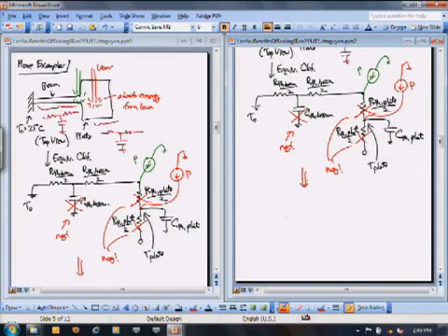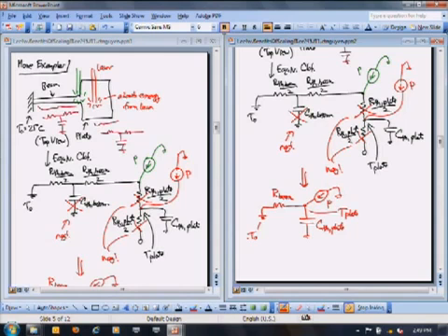where you just have the beam grounded there. That goes straight into the thermal capacitance of the plate, and the laser power comes straight into this. Okay? And this then becomes my T plate, and that's my T0. Okay? So that really is the equivalent circuit that you should be working with. Right? Taking into account the open circuits, the fact that those resistors are very small, the fact that the capacitors are very small. Usually when doing this problem, I would not draw out this complete circuit. I would just go straight from here to here. Right? Just recognizing that there's things that are very negligible in this.